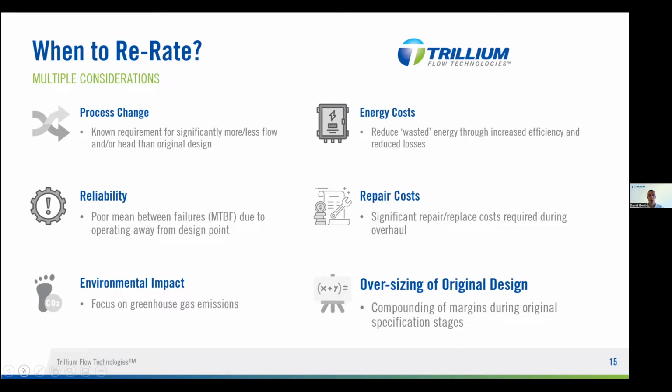Repair costs, quite often we see pumps coming in with the same problems and the same parts needing to be replaced. So trying to reduce that by designing the hydraulics better, we try and do that. And just a consideration in terms of the original design, quite often the pump is oversized to begin with, with margins added from the process teams, etc. So we're already operating off design point when the pump is first installed. So just a few things to consider.